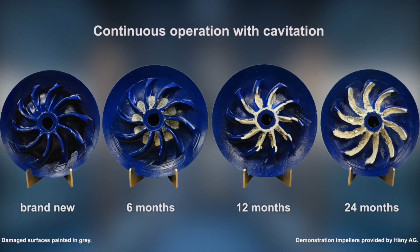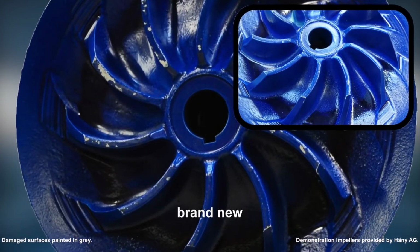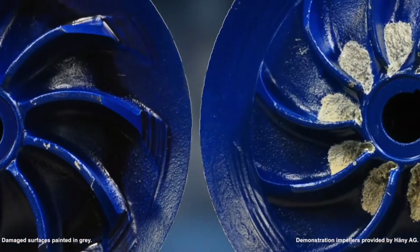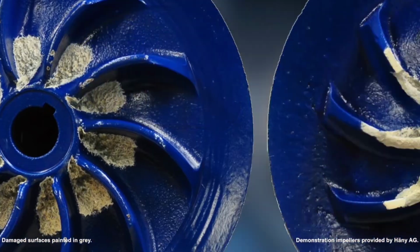There are a few examples of damaged surfaces caused by cavitation. These are images of an impeller continuously exposed to cavitation during 6 months, 12 months, and 24 months. The new impeller shows the geometry as it should be under normal operation without cavitation. After 6 months of exposure to cavitation, we can see that corrosion starts at the center of the wheel, and the impeller plate is damaged.